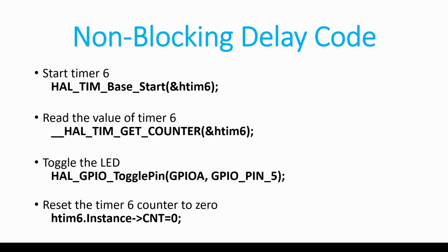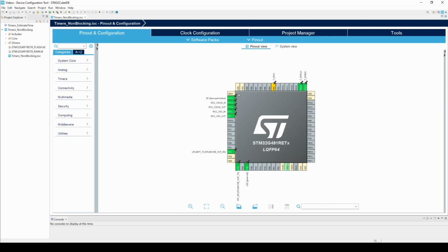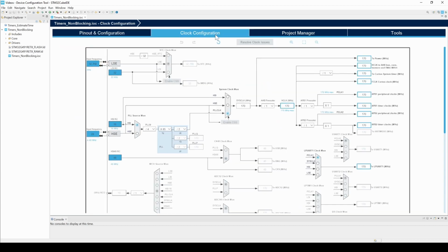Now, let's open a new project in the IDE and set all peripherals to their default mode. In the clock configuration window, we will first look to the APB1 prescaler. You may notice that there's actually a frequency multiplier located behind the APB prescaler. As soon as we start adjusting the prescaler's value, the frequency multiplier will increase to 2. Therefore, to get our desired clock frequency of 42.5 MHz, we will set the APB1 prescaler to divide by 8 so that the timer clocks will be at the correct value.